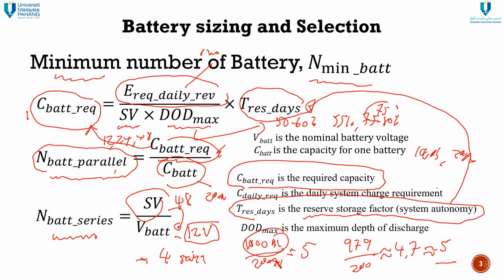Then maybe that brother who claims that he's very expert, has done a lot of projects, but maybe if they don't consider this kind of calculation, you can question, because the problem is the battery will be insufficient. Seriously, if for example you wrongly use the system voltage, for example your load is more than 4 kilowatt hours but you use only 24 volt, I believe it will be insufficient during the operation, especially for those who use heavy loads like the air conditioner, iron, or the water heater if possible lah.